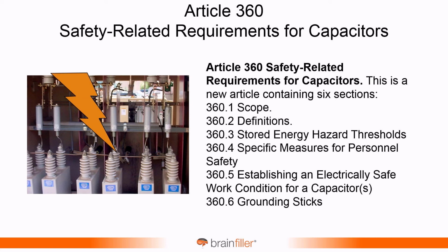Article 360, I mentioned this a moment ago. Brand new. Capacitors were only referenced a couple of times historically in NFPA 70E, but they are a large source of stored energy and quite a source of a potential hazard. And so there is a new article, it's actually quite large, that is broken up into scope, definitions, and then the stored energy hazard. That's really important. And measures for personal safety, establishing an electrically safe work condition that's specific for capacitors. It's not like what we'll call a traditional electrically safe work condition. There are other considerations that need to be made, and the use of grounding sticks.